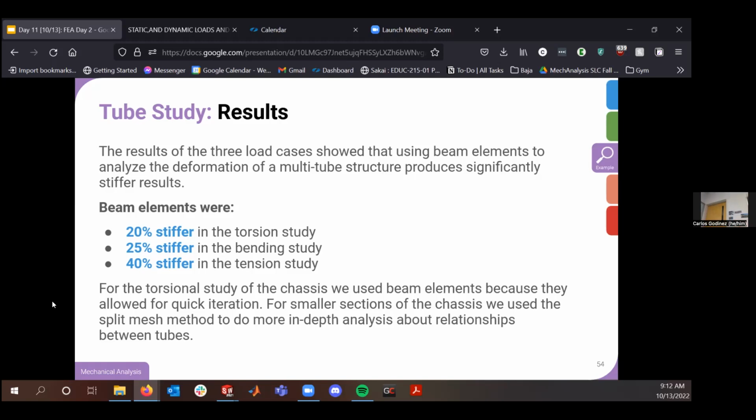That was for using shell analyses to represent gussets and welded joints and so on. And then comparing if I have one giant face or if I split it up into a bunch of squares, how does that change? These are studies that are done in an industry context as well. How good is good, and how do I compare it to my experimental results to say this FEM model is the best for what I have, versus just putting everything as solid elements and calling it a day. Oh, sorry, when I say FEM, I mean finite element method, if that wasn't clear to anyone. I'll hand it back to you.